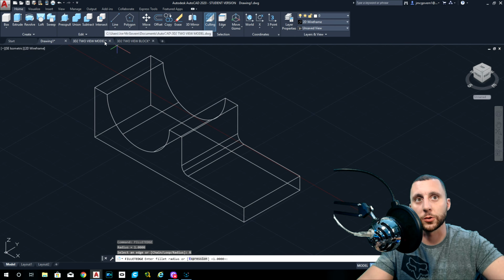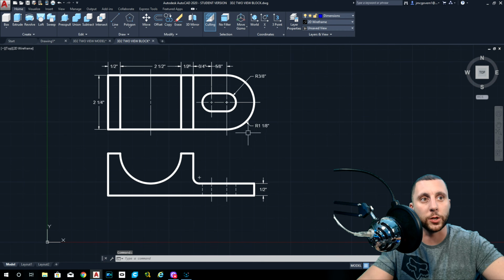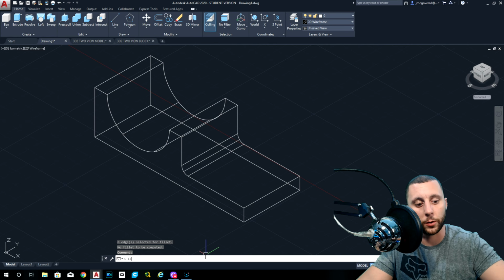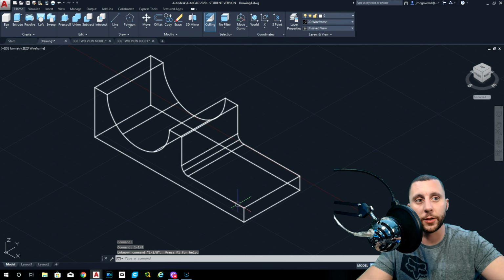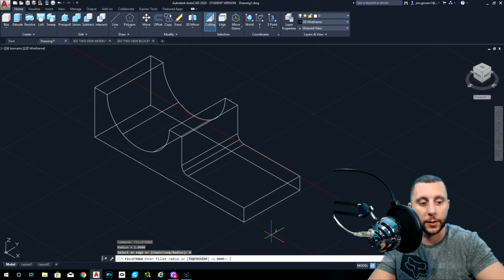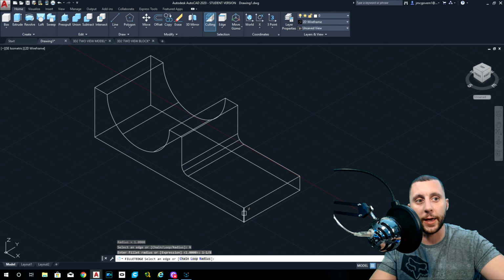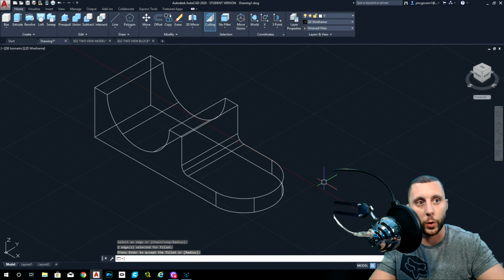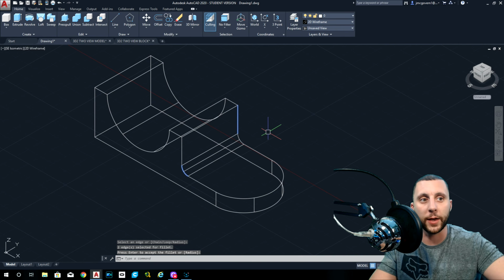We're going to go back to this drawing for a second and see what that radius should be. Radius 1 1/8 for this big circle out here. 1 1/8. And then instead of clicking 2 lines, I got to go back into that, sorry. Fillet edge, radius 1 1/8. Instead of clicking 2 lines, you're going to click the edge that you want to round, which is going to be this little line. 1 there, 1 here, and then you have to hit enter twice, okay? Once only shows you what it's going to look like. Twice actually keeps it, all right? So we've got the end rounded.